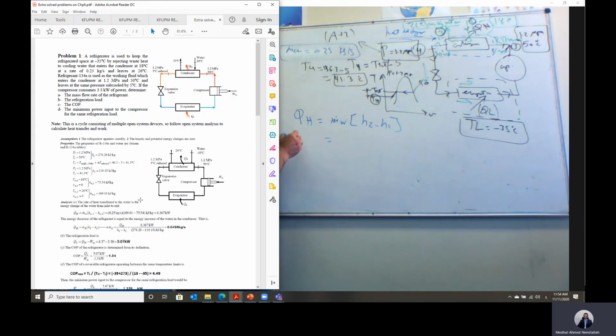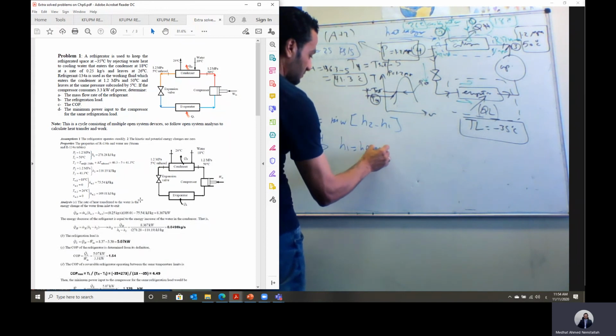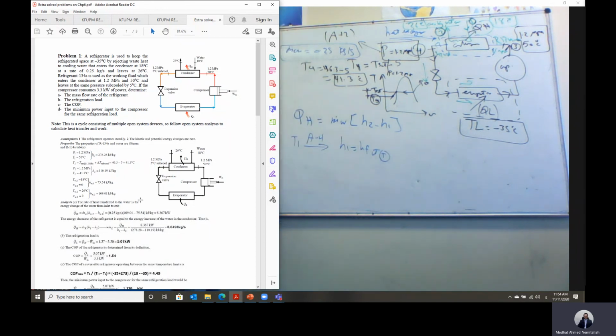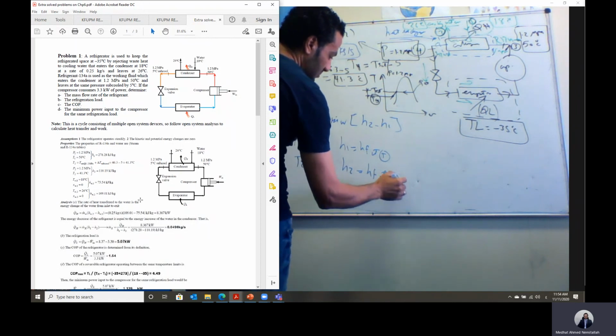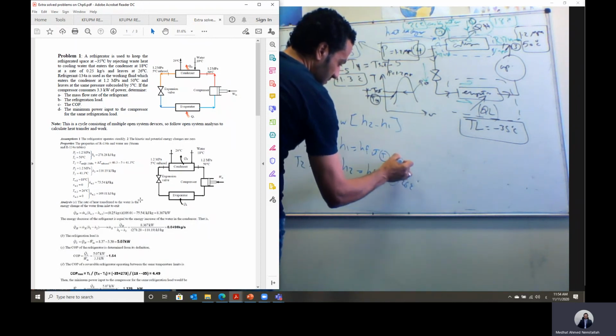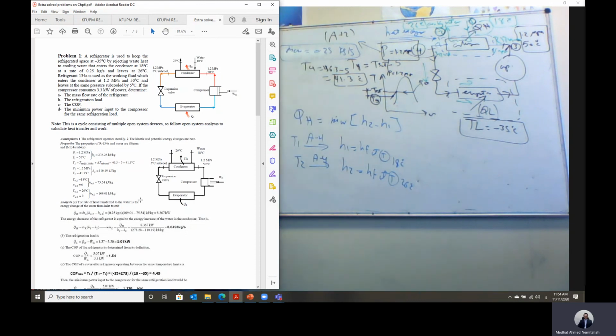So in this case, we can get the temperature T1, and we can just go to table A4. Then we can get H1, which will equal h fluid at the given temperature. In case of subcooled liquid, the enthalpy is equal to h fluid at the given temperature, not given pressure. Okay. So we can calculate the value of H1, and also T2, which is equal to 26, while T1 is 18. From table A4, we can get H2, which will equal h fluid at this temperature, 26 degrees C. This is 18 degrees C. Then we can get H1 and H2.